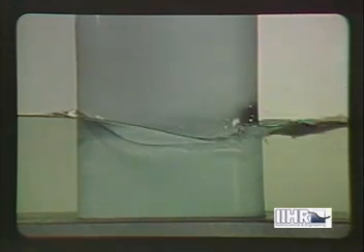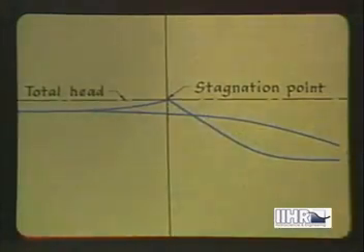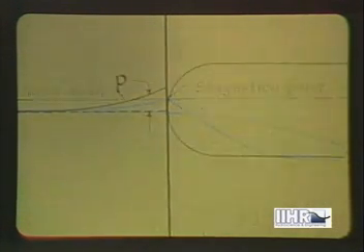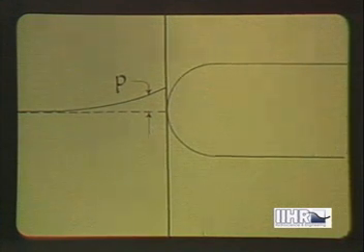Adiabatic flow can involve standing waves, just like the gravity flow of water, the flow at each section being equal to the celerity of either an elastic or a gravity wave under the corresponding conditions. If free surface flow approaches a zone of stagnation, say on the front face of a pier, the surface will tend to rise in a standing wave to a level coinciding with a line of total head. Much the same thing occurs when a gas approaches a state of stagnation, say at the nose of a pier or pitot tube. But the temperature rise now causes the pressure rise to be still greater.